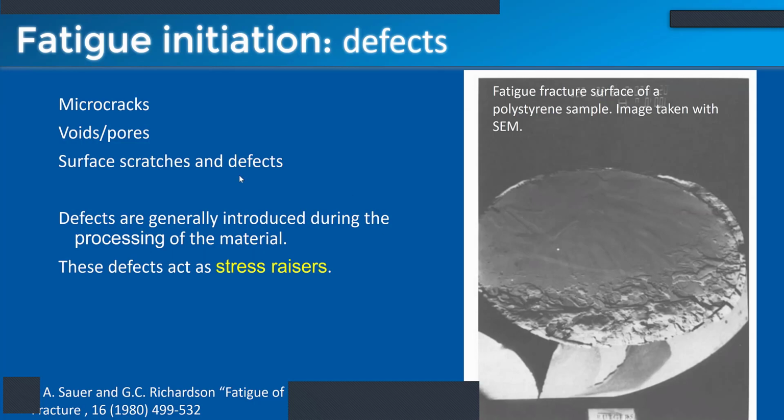And that occurs because in fatigue failure, the stress that we are applying to the material is less than the yield stress. If it was greater than the yield stress, we would probably have this ductile fracture type of pattern. But because we keep the stress under the yield stress, which we should, and we are cyclically loading the material and unloading it over and over again, we eventually get failure, but that failure happens when we are lower than the yield stress of the material. And so our fracture pattern looks different.